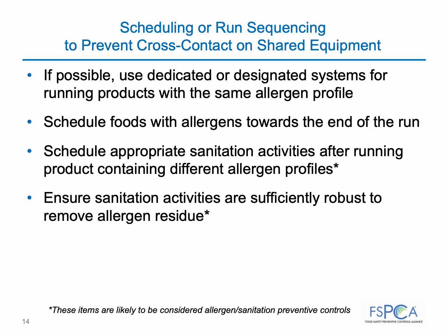Common industry practices for using scheduling to help manage risks from cross-contact have been published by the Food Allergy Research and Resource Program, FARRP, which includes the following. Schedule long runs of products containing allergenic ingredients to minimize changeovers. Segregate production areas for allergenic and non-allergenic products.